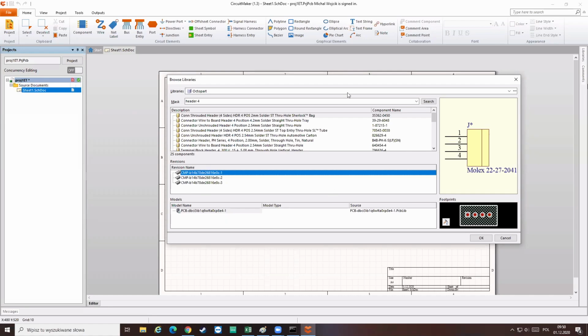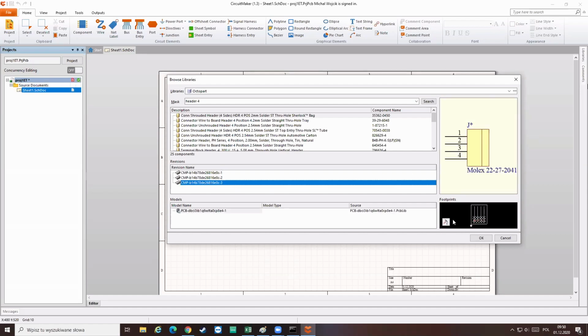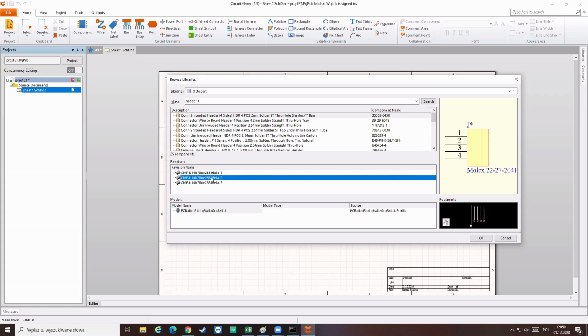And there are also revisions of that. In case of this online sharing stuff, you get revisions of the elements. If this component really has such numbering, and you can find it in Google by that, it's some trademark, maybe actually it's in the description, then someone has revised it and made a correction so you can choose between revisions. And then also for some elements, there will be different footprints to check. The schematic will be one, but footprints here is only one for each revision, but originally for resistors, etc., there can be more models to choose the footprint from, because some resistors can have various footprints, or some MCU can have various footprints. Okay, let's go with this.